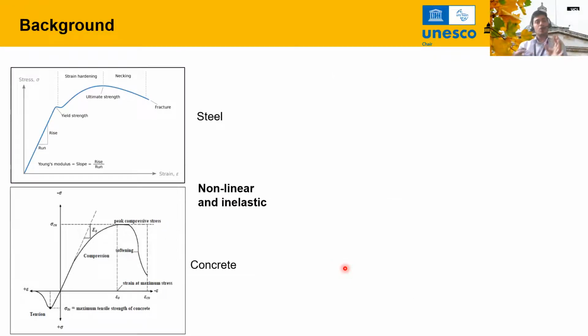So our structural materials, for example, the steel or the concrete or even masonry, all perform non-linearly during extreme loading. For example, if you see a stress strain diagram here, for low level of loading, the behavior is elastic in both cases, but under extreme loading, for example, the earthquakes, the material, the structures go into nonlinear range.